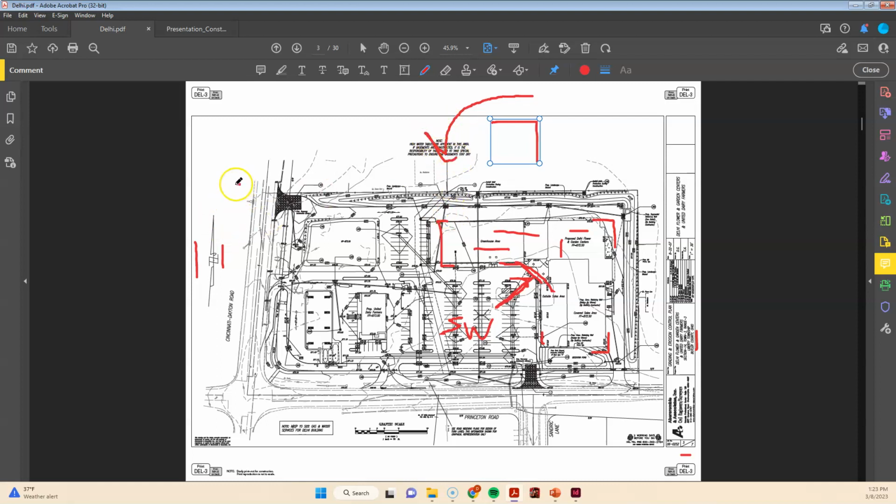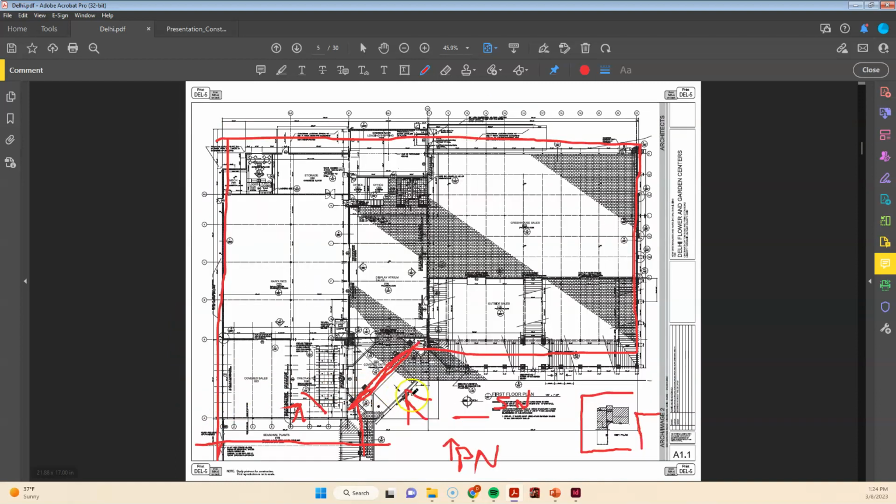counterclockwise? Yes, because now when we move to the architectural plans, the north arrow has changed and is now facing what I would call maybe plan west, or the west side of the sheet, so to speak, right? This is the west side of the sheet. So the difference between solar and plan, and how a project could be rotated from civil to architectural drawing. It's very important to know that, okay? So here, north is over here, which means that this is the east now, this is the west, and this is the south.